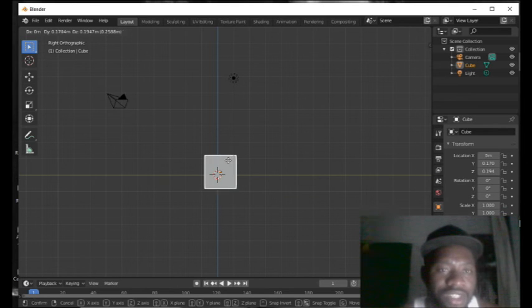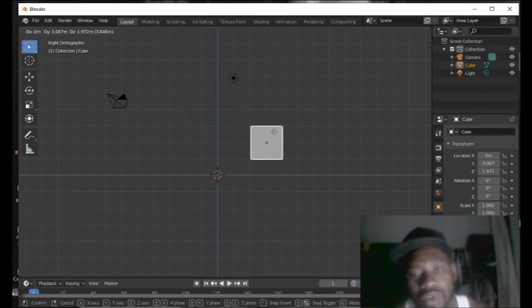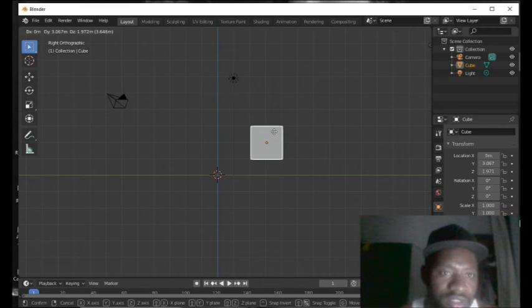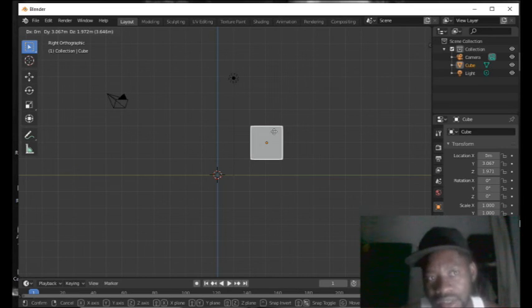The software automatically calculates the position where you place the object. Now if you see, we moved the object to this point and you look at the topmost left-hand corner, you will see all the axes being labeled there. We have dx 0 meter, dy 3.67 meter, dz 1.29 meter. So where is the z, where is the y, and where is the x? The x is pointing directly into the plane, so we cannot see the x, the y is moving from left to right, and the z is moving from down to up.